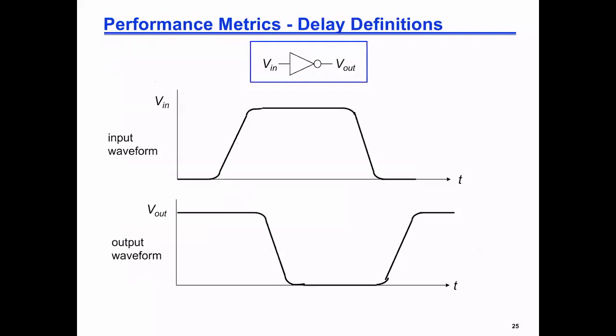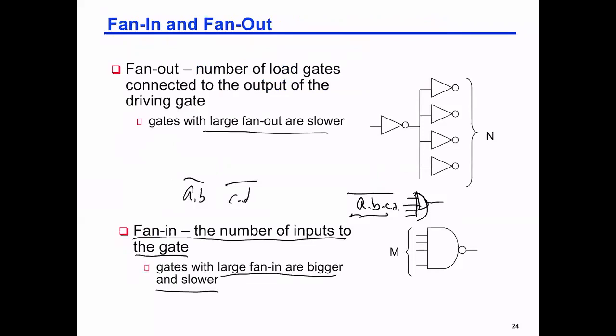Sorry. Yes. In the fan out example, so you're saying that the inverter's performance depends on current also? What we will learn later is that each one of these inverters will be some form of a capacitive load on my design. And if I want to send the signal A to many outputs, and I'm loading this inverter with many of them, the equivalent capacitance driven at this node is large.